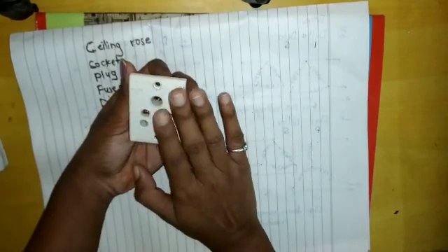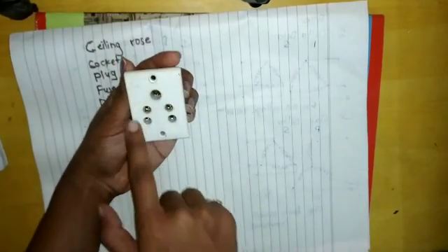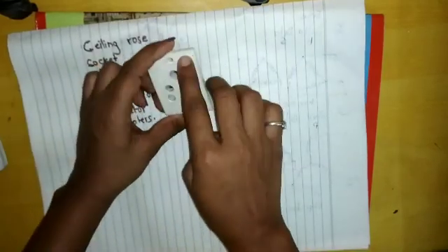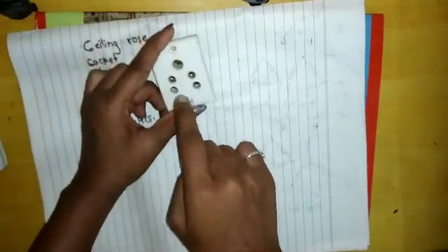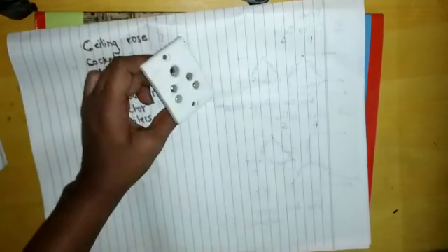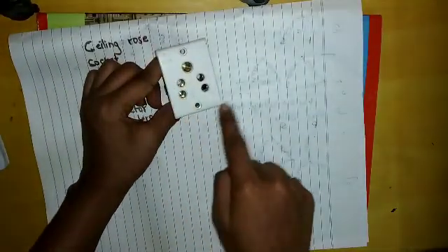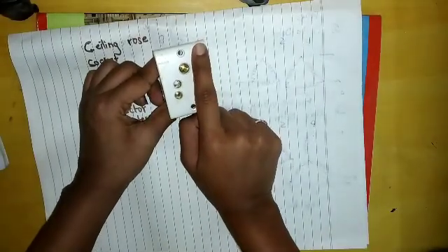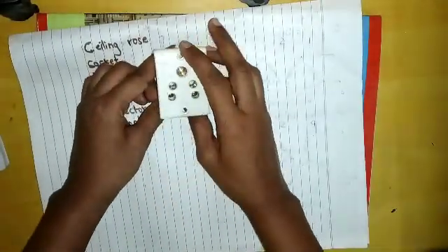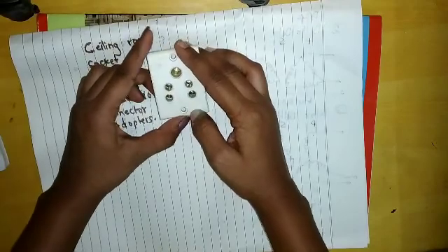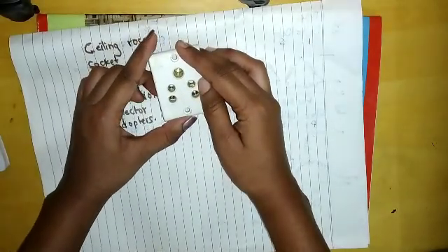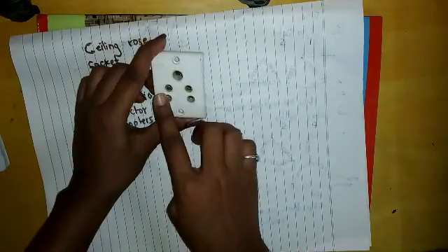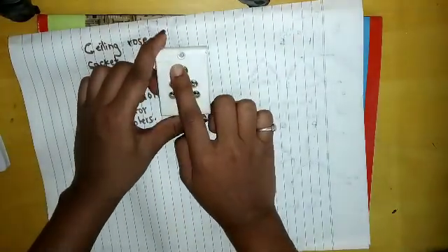That means if we have to connect any apparatus, we first plug in that apparatus, right? Sockets have insulated base. Here the live wire will be present, so whenever we touch the outer side, we must not get shock. So this is made up of porcelain base having 3 terminal sleeves. Two terminal sleeves are made for taking connections to the cable, that means phase and neutral, and 1 terminal is given to the earth.